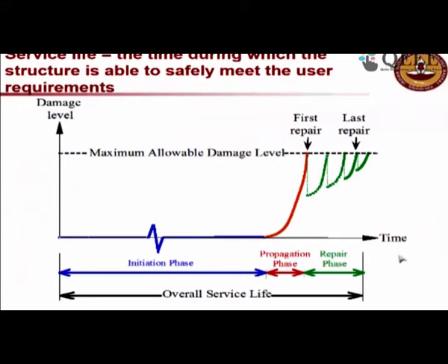I will briefly go through the service life prediction. So what is service life? When you say durability of concrete structures, if you want to talk in terms of some numbers, we have to bring in some numbers in terms of life, or number of years, or time for which the structure will meet its requirements in a safe manner.